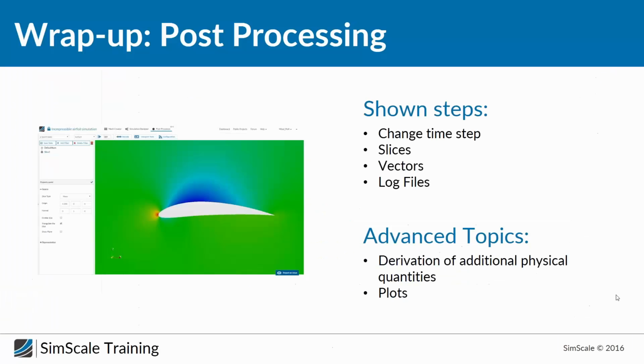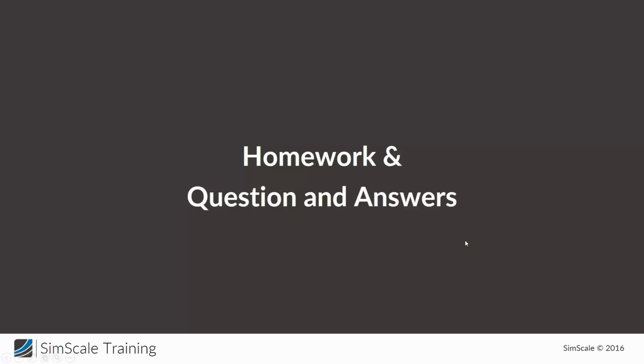Okay, then I will now introduce you to your homework, and we have time for question and answers. Let's just take a question I would like to answer by Muhammad. He wants to know if the default quantities for schemes are good for solving different types of problems. Muhammad, basically the default settings were chosen in a way that they work for most of the cases, but if you know your simulations are maybe a little bit more special, you should take a look at the library, look for a similar simulation, similar kind of physics, and then maybe copy the numerical settings or just write in the forum.